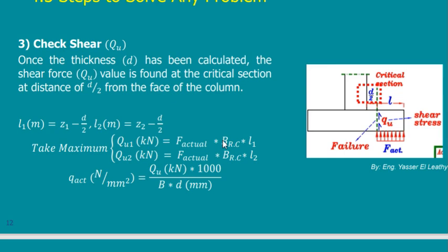So shear is part of the foundation leaving the main foundation. But punching means the column pressing hardly on the foundation, all around the column, and penetrates the foundation. So this is the sense of what is the difference between punching and shear. They are both shear. It is all shear stresses, but in different ways. So the allowable here is different than the allowable here. So people from the RC department give us some codes and some equations to use.